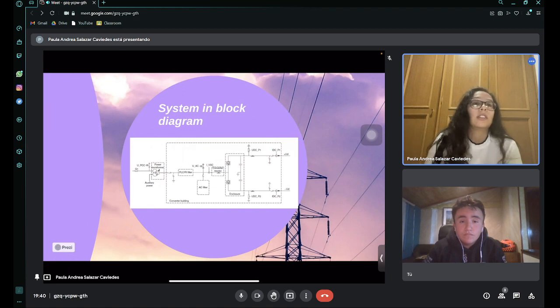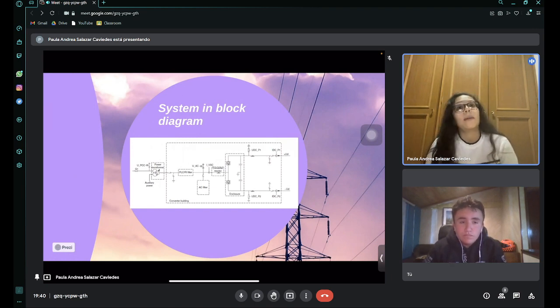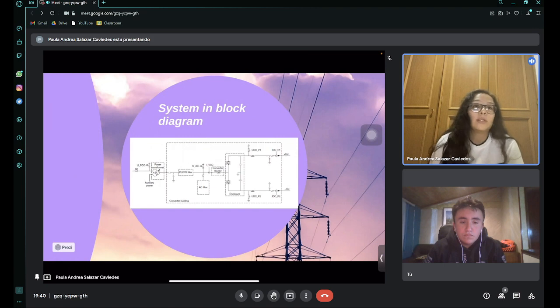Normally, the uses for this part are to provide a low pass filter of PWM, to give the desired fundamental frequency voltage. Another is to provide active and reactive power control, since the fundamental frequency voltage across the reactor defines the power flow. And the last one is to limit the short circuit currents.